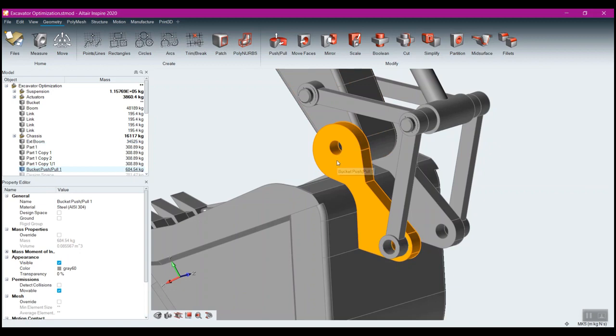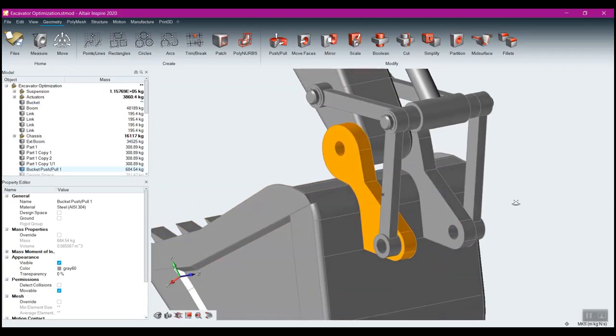So making sure that the loads are correct would be very, very difficult on this, but it's actually incredibly simple with motion. Since we run the motion analysis first and then indicate how we want to go about doing an optimization, OptiStruct, the engine behind the optimization, will pull the loads from the motion analysis and string them together. So we're not only getting an optimization based on loads that we don't know, but we're essentially getting an optimization out of a dynamic system, because it will take a look at all of the loads through all of the different stages of this analysis.